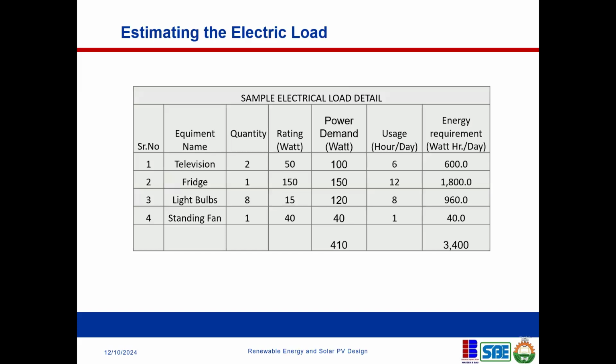So first of all, the purpose of having a PV system is to serve a certain purpose, and that purpose is to meet electrical demand. So you usually need to start from the demand. You don't start from the supply. Now, PV systems are supply side, right? They supply electricity to the demand. So you need to start from the demand. What exactly do you want to size?